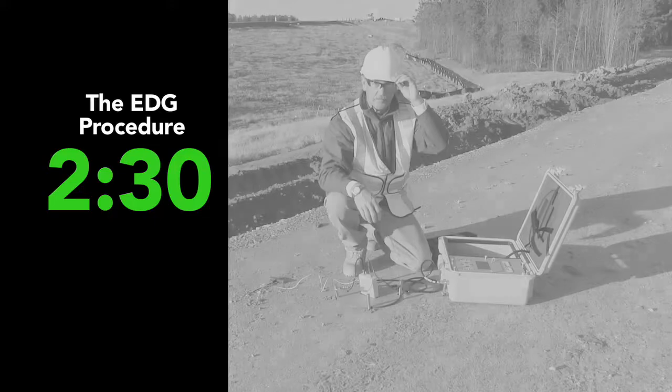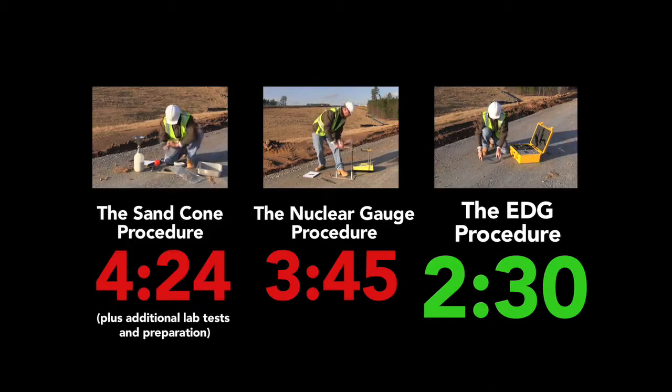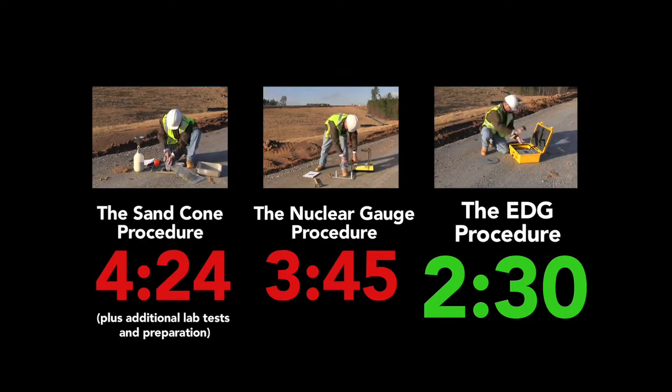As you can see, the EDG is actually the fastest of the three methods, with the nuclear gauge and the EDG being closely matched, especially when using fast mode measurements with the nuclear gauge. The sand cone, however, involves a longer test time, as well as the added time involved in weighing samples and performing moisture tests in the lab.